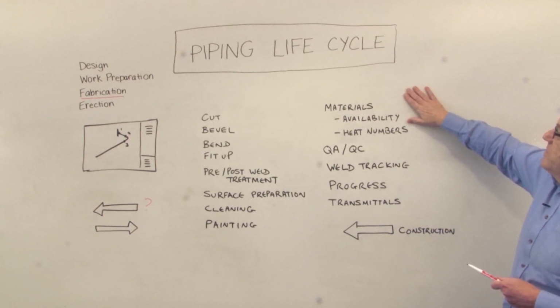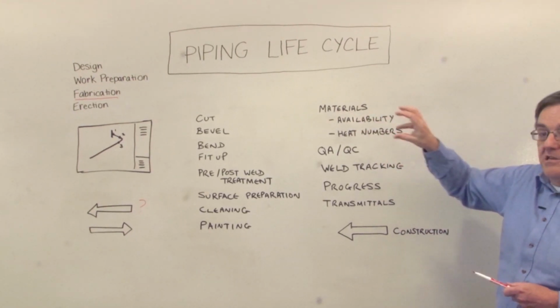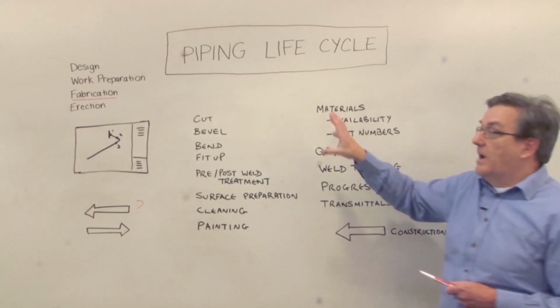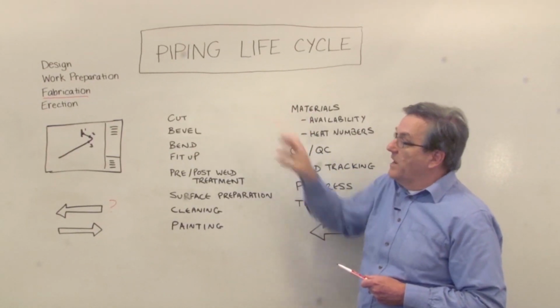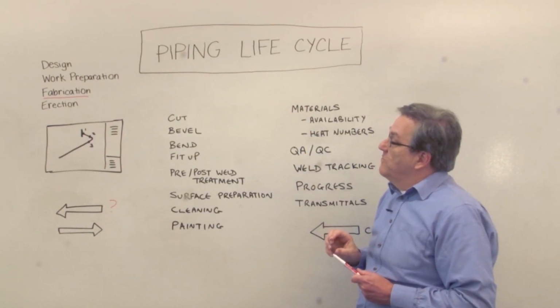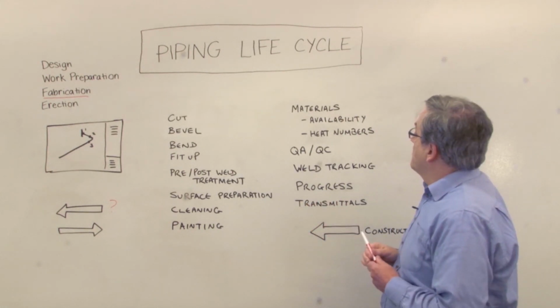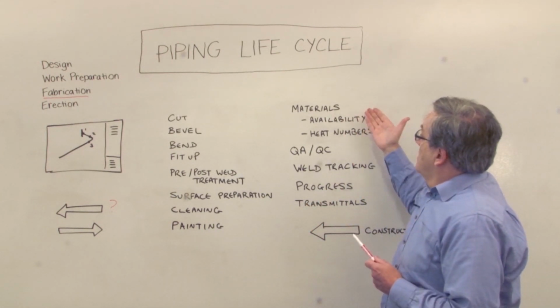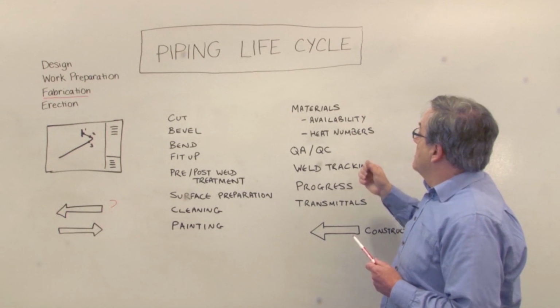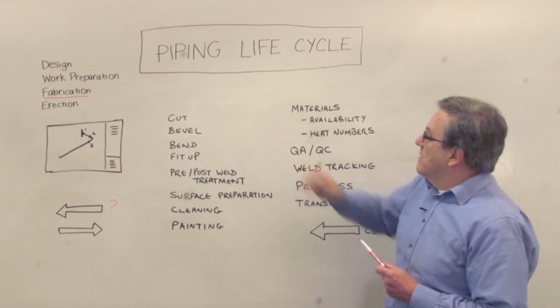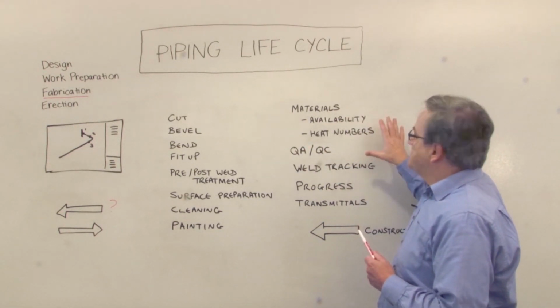All sorts of issues follow. In this particular example, we need to make sure that the elbow and the flange are available for the spools to be fabricated. So availability of material is a big issue, and that can tell us what particular spools we need to make.